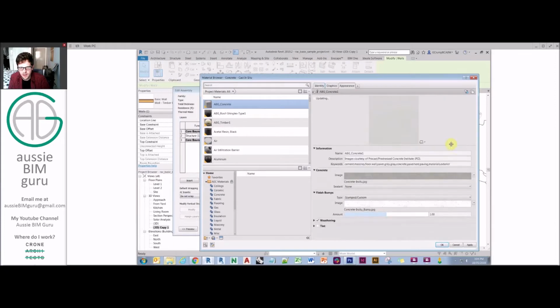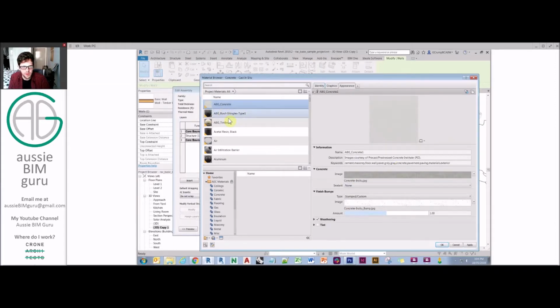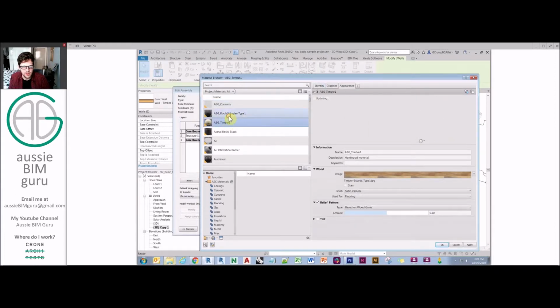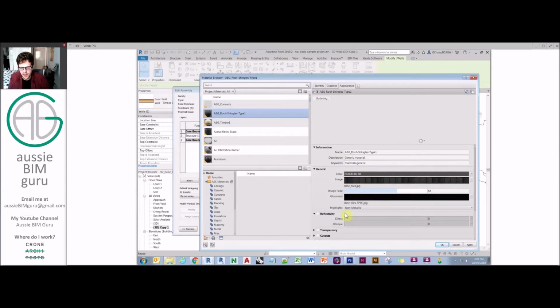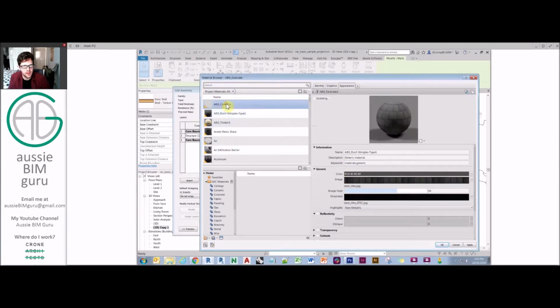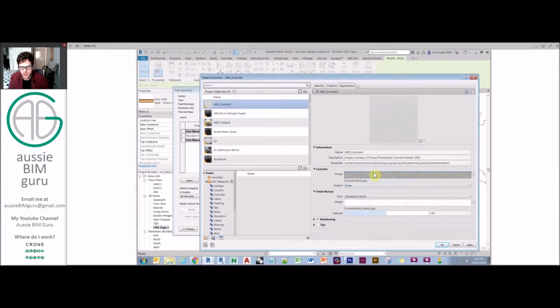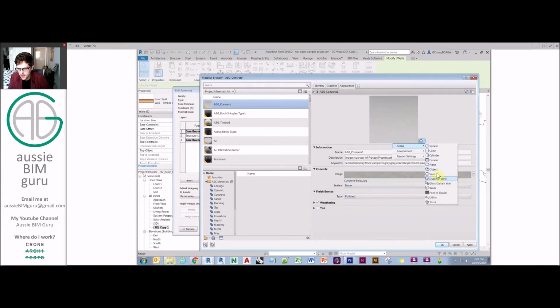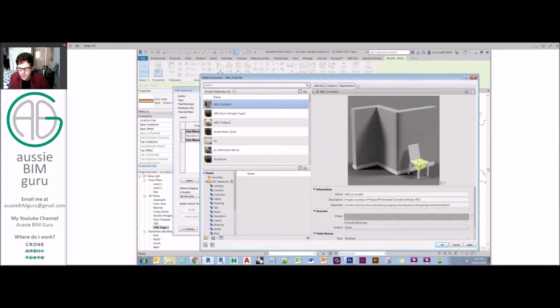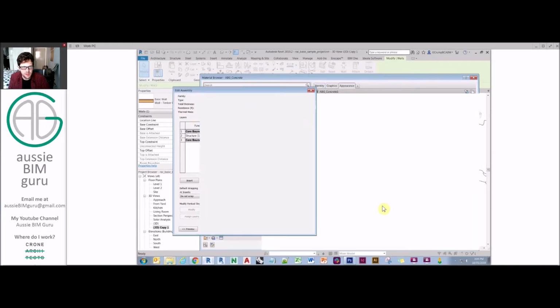So you may have certain preferences, in which case I'd recommend you use an expanded asset, one that has all these map channels available. Because you'll notice here I can't put in reflections, so I couldn't do a polished concrete floor if I so chose. But you do have certain qualities of what you can do to the floor itself. So if I just make a scene in here, such as a wall which has a chair, you can roughly see that it's coming out quite nice. So we'll just say that all our concrete is polished in our scene.